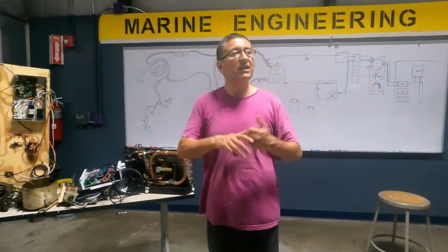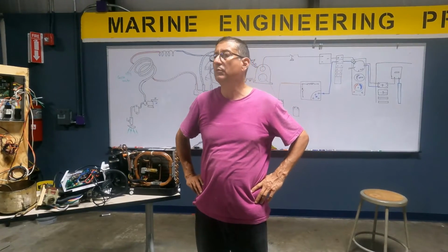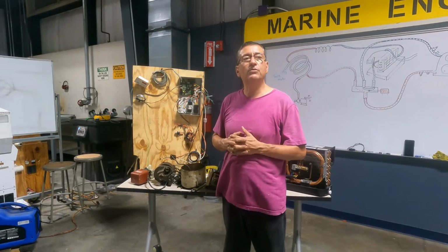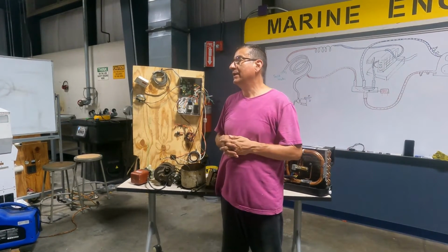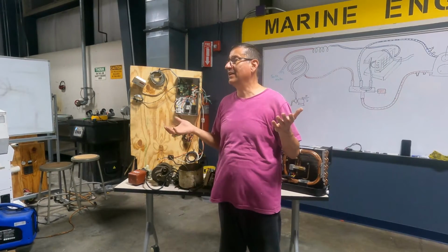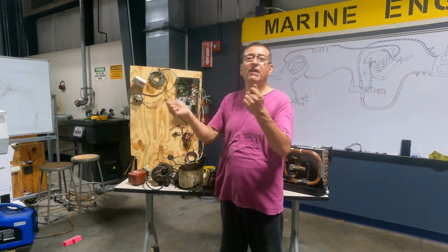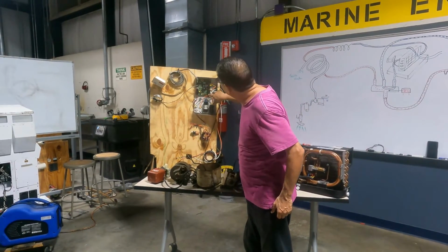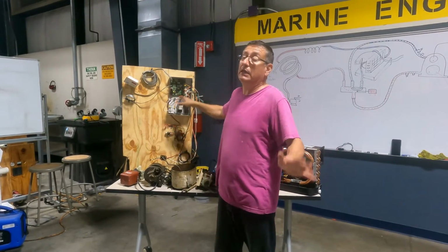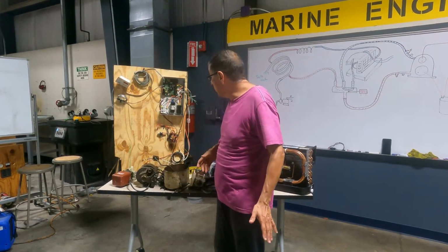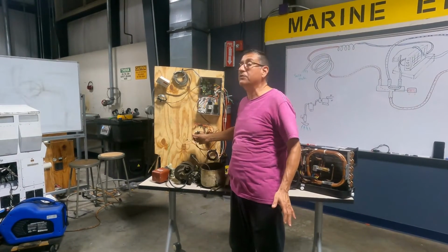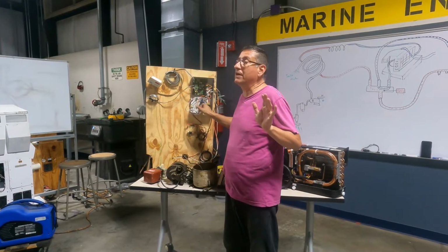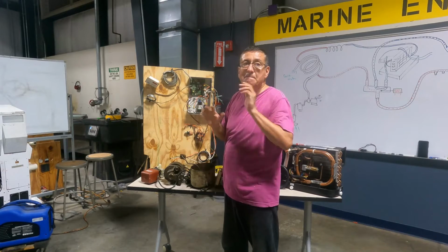When you receive the harness, replacing the harness is too simple. Always you need to check the pressure with the pressure gauge. If you don't have a pressure gauge, you cannot diagnose the air conditioning unit. Some people say, no, I have the multimeter. Okay, with the multimeter you can check if you have the power coming in phase 1, phase 2, and neutral. After that, probably you can check if you have power at the input of the compressor in the thermal contactor. And that's it. Or probably you can check the condition of the capacitor with the multimeter. And finito.